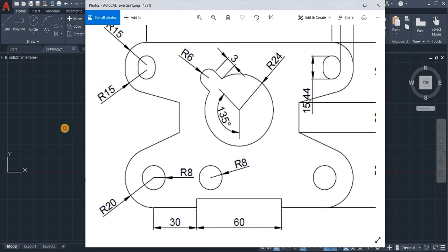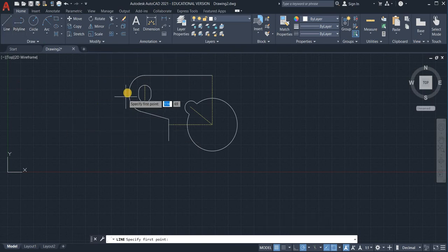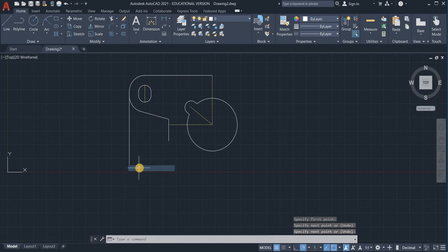Alright, so I think we've got all the information we need to keep going with our drawing. So let's get the line tool, and I want to draw a line that is straight down. I didn't really pay much attention to how long it was. I'm going to do that with a construction line that I draw from the end here and come down, and it's 50.